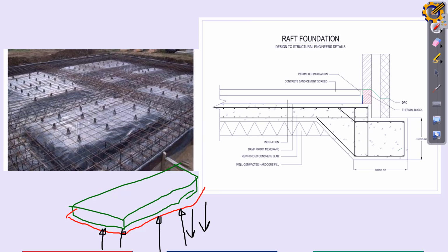But imagine there's nothing like that in your building. It is just anyhow, they just do it, park their load, and go. If the soil is not that good, anytime there is rainfall like this, water starts rising, and that is why you see some buildings whose walls get wet. When you apply painting or any finishing, it will be peeling off. It is because the soil water is the one destroying it. That building does not have a DPC.